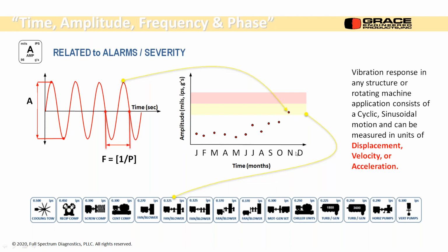Now, this is just January through December. This would be a route-like measurement. Walk around routes, you take your data every month, you log it into the database, and you get something sparse like this. If you're using a wireless transducer, you can command it to do it once a day. You can take data once an hour, what have you. So let's say we're taking it once an hour, and in a month, that's a lot of data points.